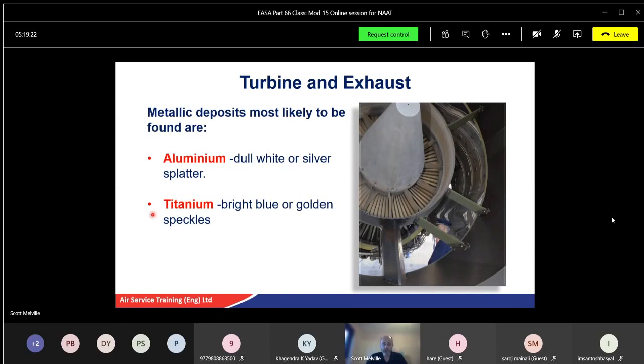We did a service on one jet down south. The pilot was doing his walk around, and he looked at the back of the exhaust, and just by chance the sun was right behind us, so the sun was really bright and really lighting the exhaust. You can actually see a lot more than normal, and it's always quite a dirty environment where the thrust reverser is. And the pilot goes, I think there's something wrong. So I'm looking, I'm going, no. He says there's something different. I says, the only thing that's different is we can see it more clearly because the sun's behind you. He says, I've never seen it that clean before. So he thought there was something wrong, only because it was better light shining on it. Okay, so again, make sure you've got decent light to see what you're looking at.